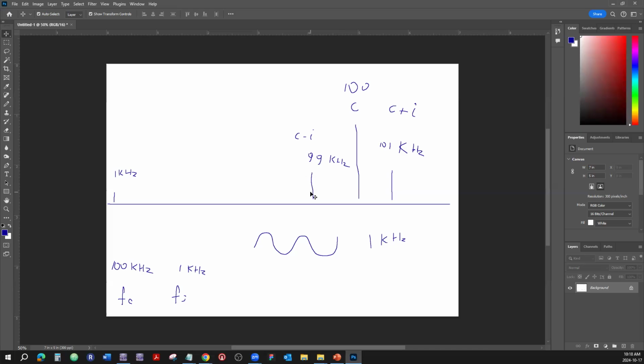Now, that we're going to take care of next time we see each other in the lab. See what this thing is going to look like. We're going to connect a microphone instead of the second generator, and we can speak to it and see what that FFT shows us as the side bands, because the sum of the frequencies is called the upper side, and the difference of the frequencies we're calling the lower sideband. Upper sideband, lower sideband.